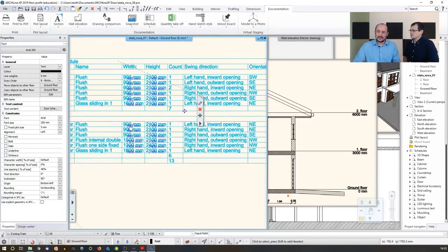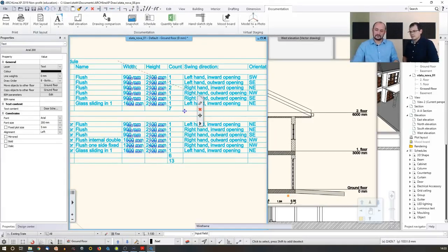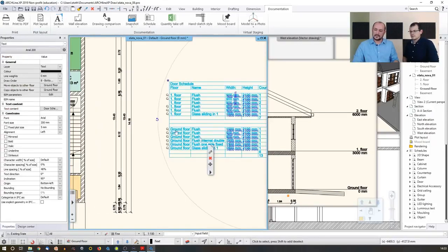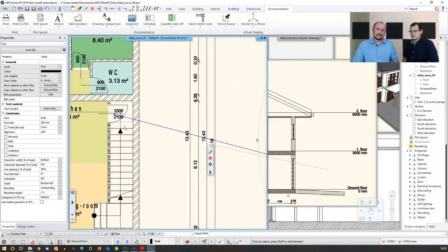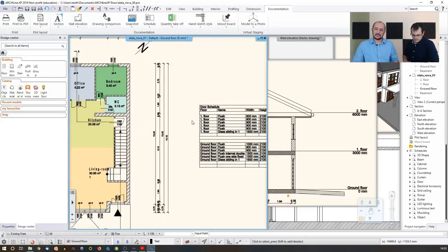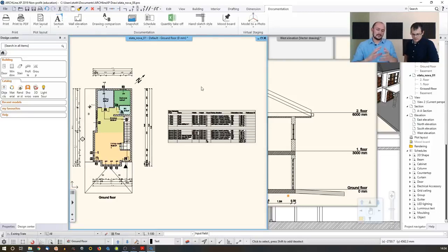on this level. But if I click here, and for example, again, there was a change in the drawing and I need to change it to 1000, I can just change it here, because obviously in the list I would like to see an updated value. And then now that it was updated, the software also updates the content. So let's see, if I click here, let's find it again. So see, now the door also gets updated. Does it work both ways? Yeah, if I update this here, it will also update the content on the right-hand side. So the schedule is in a bi-directional connection between the content itself and the door. So whichever you change, it will update the other one.